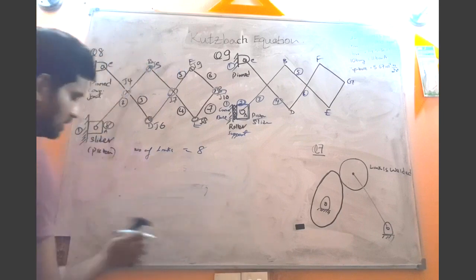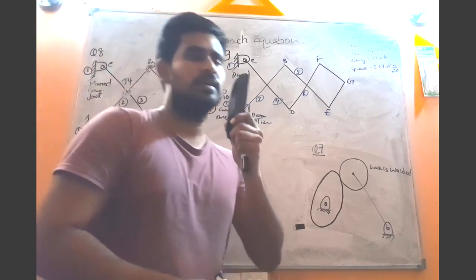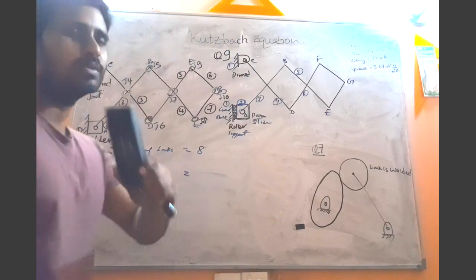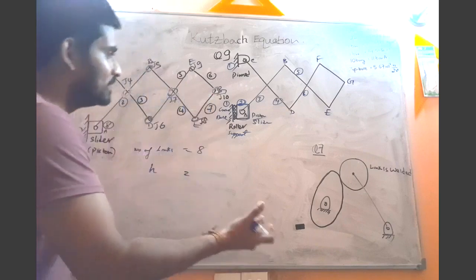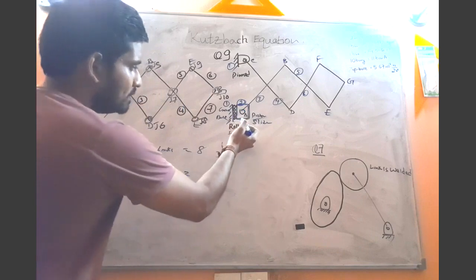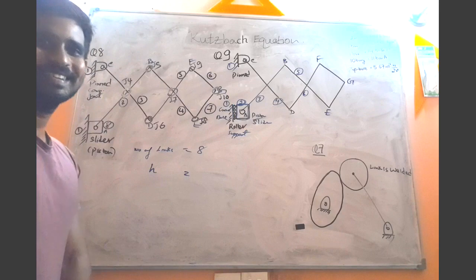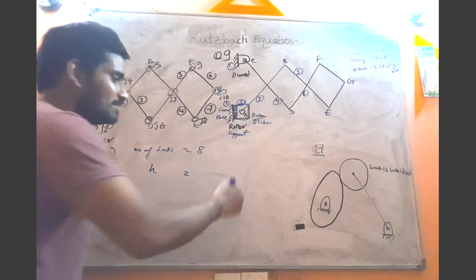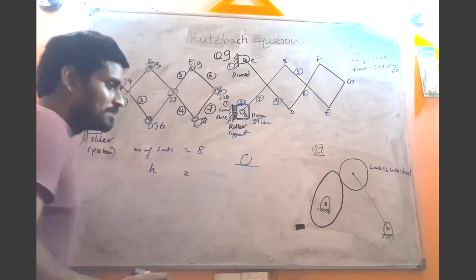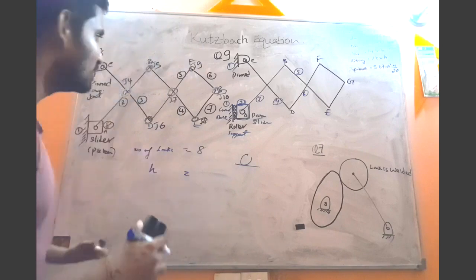Now be very careful. The next target is to find, let's focus here, do we have any higher pairs, HP? Yes, we have one higher pair. That is the interface between this piston and the base. So there we have a higher pair, something similar to the connection between the tire and the road. Such types of connections we call a higher pair, right?